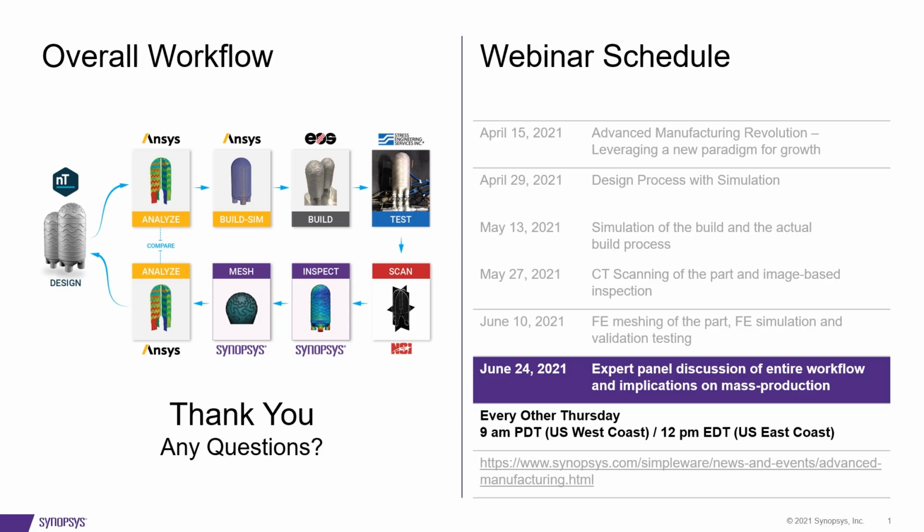In Mechanical, we have improved the STL-based meshing capabilities specifically for these kind of applications coming from additive. But overall, I would say the cleanest way to do that, with a lot of control, if you are into meshing with details, is something like Fluent Meshing, which has great capabilities for STL.